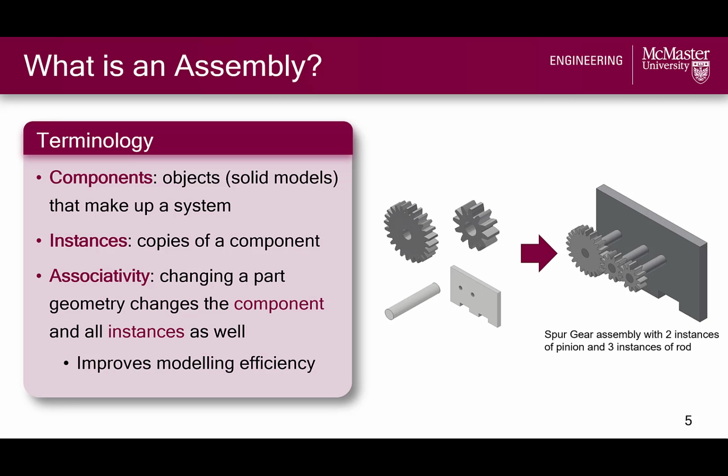Another important term to be aware of is associativity. A feature of Autodesk Inventor is its associative design, meaning if you go and change a component's geometry in its part file, all of the instances of that component in your assembly will be updated as well. This can be handy, especially in iterative design, when you might be updating parts and you want to see those updates reflected in your assembly automatically without having to redo them.